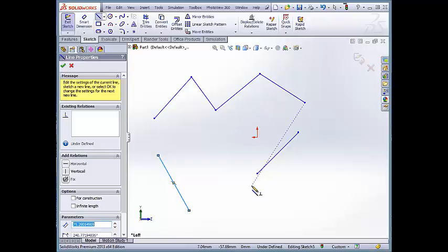Let me clear this sketch by deleting these lines. To delete sketch items, all you have to do is select them and press delete on your keyboard. This can be an annoying stumbling block that trips up many new users. To select something in SolidWorks, you click on it. However, because I still have the line tool activated, when I click on these lines, I end up beginning a new line. Typically, a new user will notice this, and to try to avoid this new line, they'll bring their cursor back to the beginning very carefully, hoping that SolidWorks will forget all about the new line.